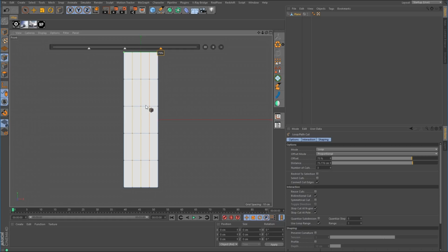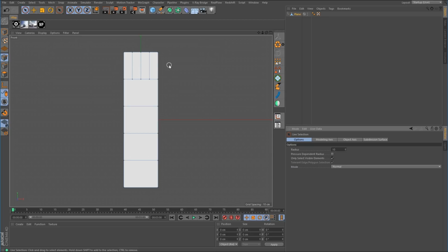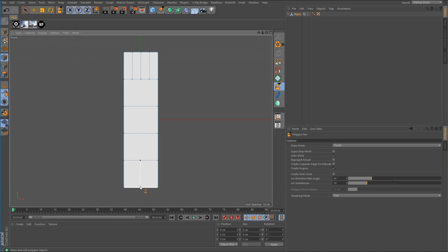But in order to kind of get around this, you got to come back down here and take the range up and then back down, and then it makes those cuts there. So if I were to go up here and reduce it again, you can see once again it's kind of messing up there, and the cut's going all the way down. All right, so we got 4 up here, and we want to go down to, I think it was 2. So we'll split the bottom one off at 2. And again, I'm going to try to solve this one up here in that second face.